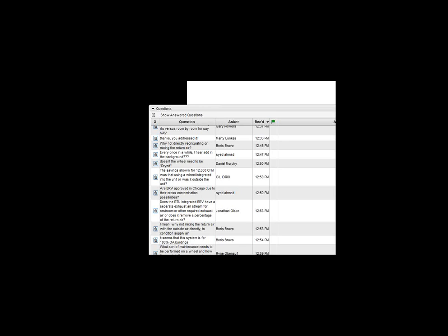The second part of the City of Chicago code says that if you're using certain classes of air, specifically for this example, toilet exhaust air, then I can't have the wheel in successive cycles of the airflow. Basically, they're saying you can't have the core, the heat exchanger, in motion between the two air streams for certain classes of air. So if I want to do an ERV on general exhaust air, I can do it with a wheel. If I want to do it on toilet exhaust or something more caustic than that, then I am prohibited from using a wheel, and I have to do it with a fixed plate core.